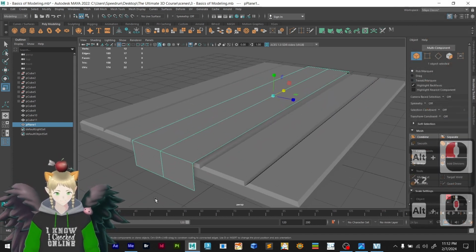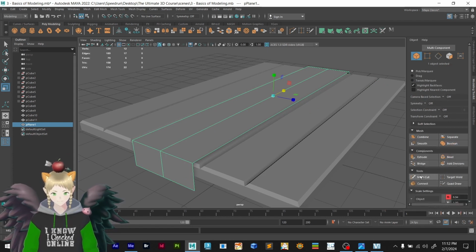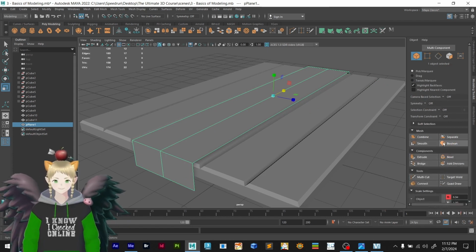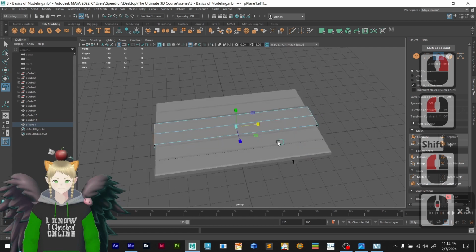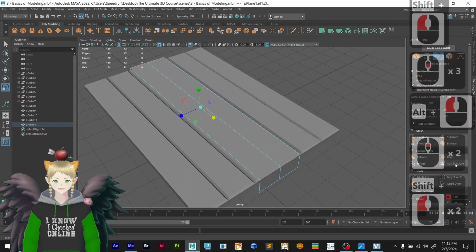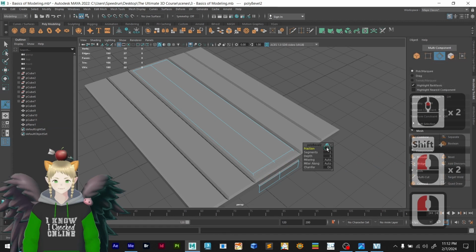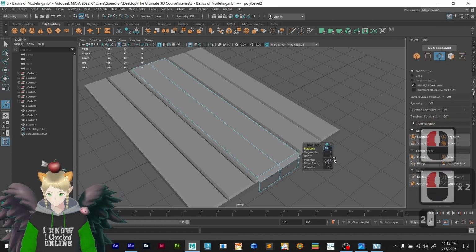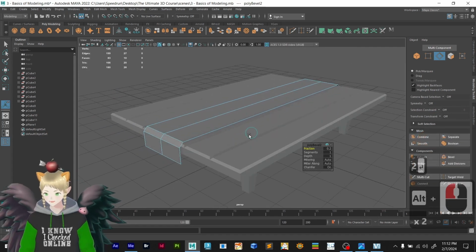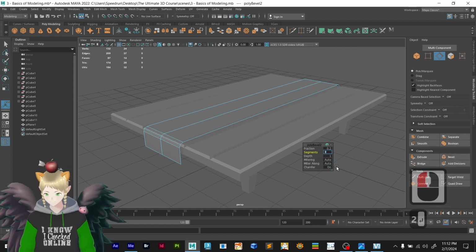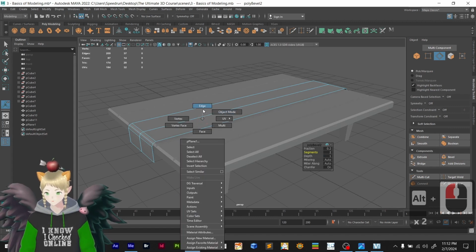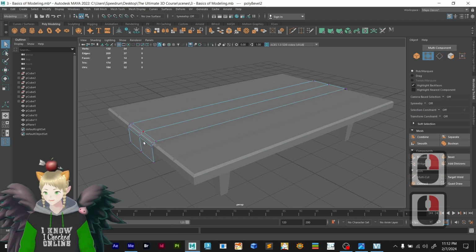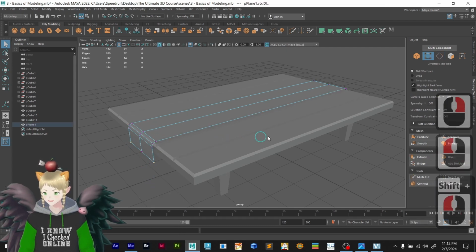Now I'm going to select these two edges and bevel. Let's go ahead and select those two edges right here and right here. Let's bevel this as well and choose 0.2, the same as the table. Now it's actually falling down nicely. We could even give an extra segment here. Let's have a look, so it feels more like a towel. I'm going to go ahead to edges right now, or let's go ahead to vertex. I'll select these 4 vertices right here.